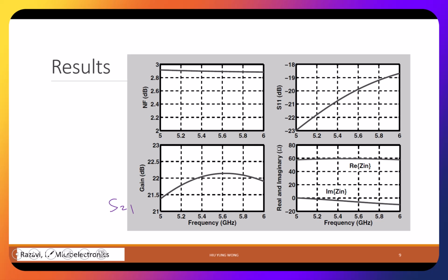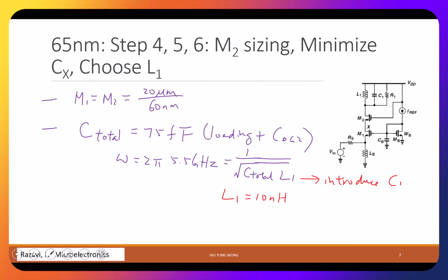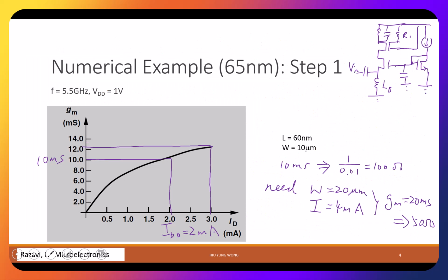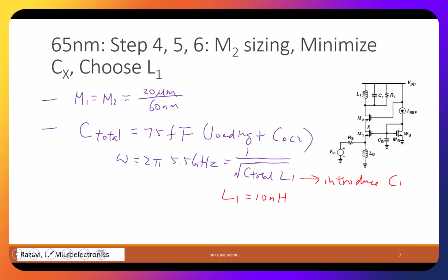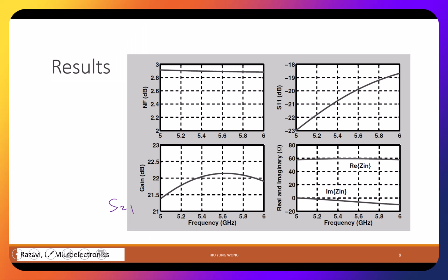You do. You need to change everything. You need to start from scratch. Because think about gm. It is already different at 77 Kelvin, right? So you cannot have the same bias to get the same gm. However, because you're supposed to have built your equations in a worksheet already, you just need to enter the numbers and rerun it. So after you've done the 300 Kelvin, 77 Kelvin, since I do not push you to improve a lot, should be quick. Maybe 2 hours, within 2 hours you can get it.